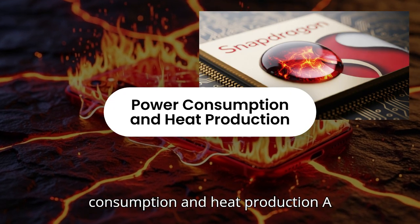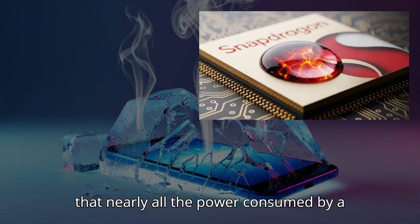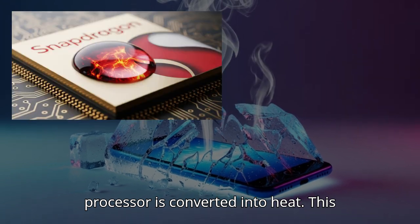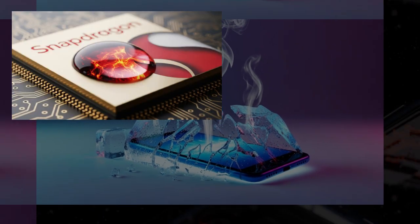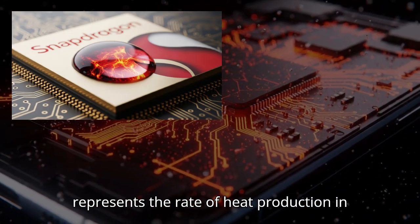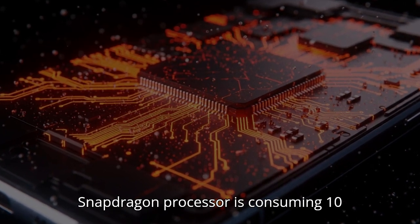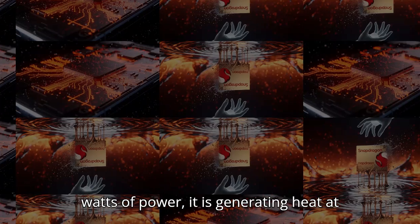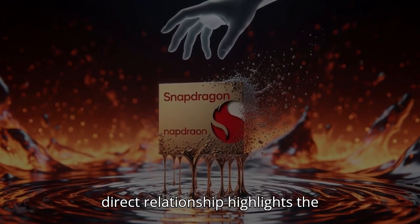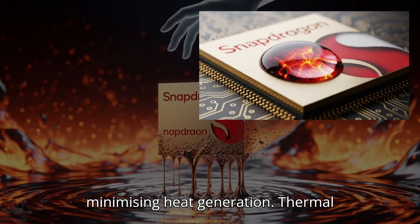Power consumption and heat production. A fundamental principle to understand is that nearly all the power consumed by a processor is converted into heat. This allows for a straightforward calculation. The power draw in watts directly represents the rate of heat production in joules per second. For example, if a Snapdragon processor is consuming 10 watts of power, it is generating heat at a rate of 10 joules per second. This direct relationship highlights the importance of power efficiency in minimizing heat generation.